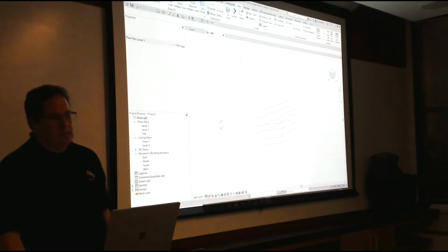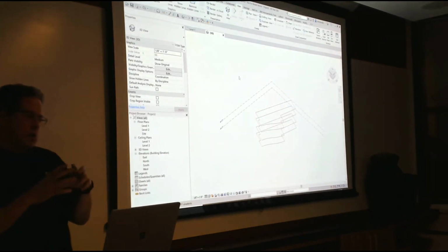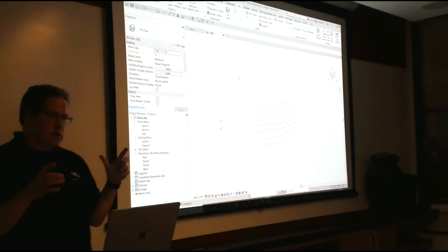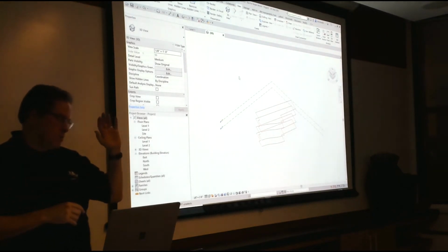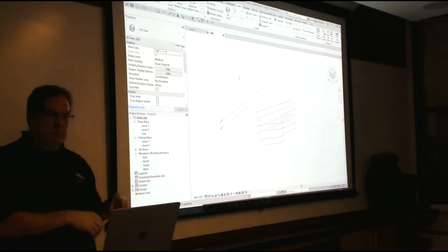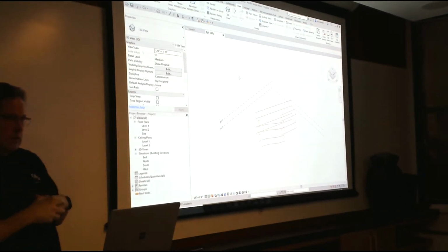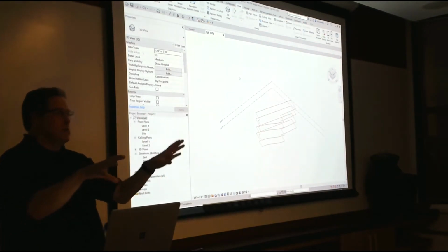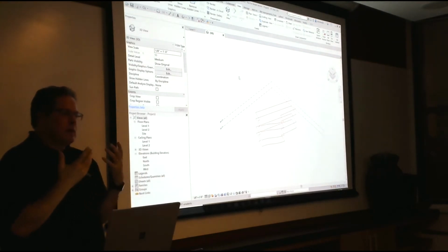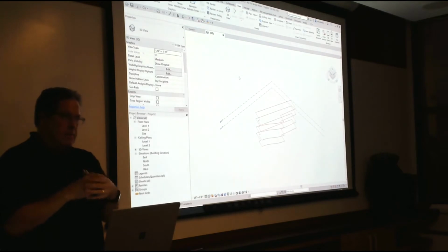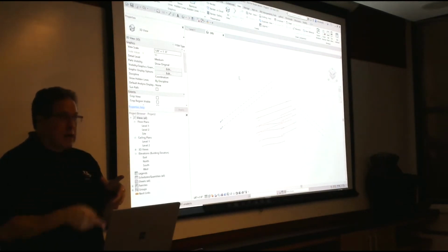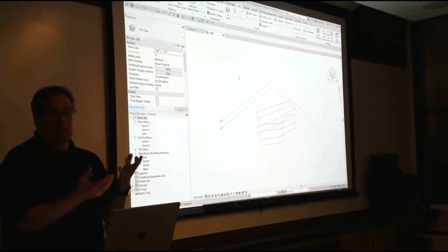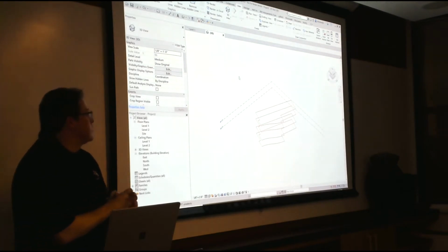Some of that might be great. So currently, that's called element binding. And currently Grasshopper, if you're in the same session, will remember the IDs. So if you go and replace stuff, it knows and just keeps your same ID. So stuff hosted on it will stay hosted. But if you save those floors in Revit and you save that information in Grasshopper, you now have it in both places, right? And so when you bring them back up, currently it would duplicate those floors. Unless, in the short run, you tag those objects, saying these are Grasshopper objects and I want you to delete them. You can have Grasshopper do that just through a parameter, right? You put your own parameter on the objects.